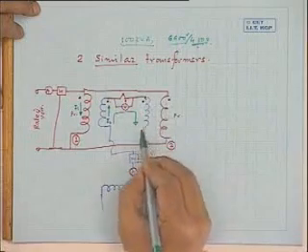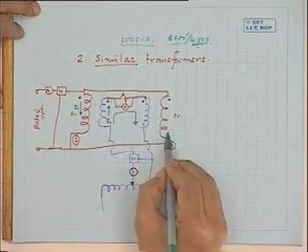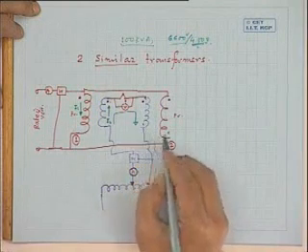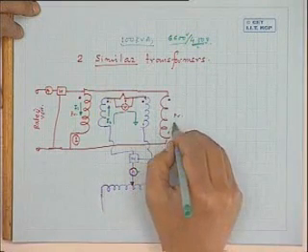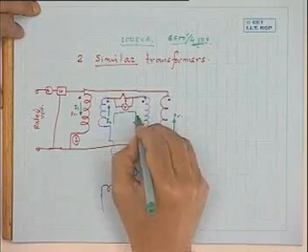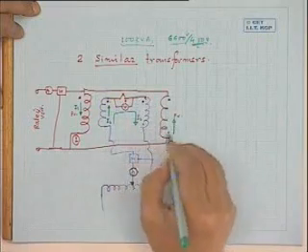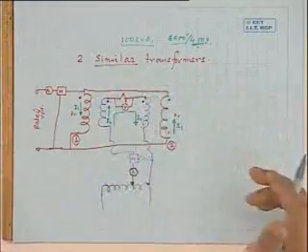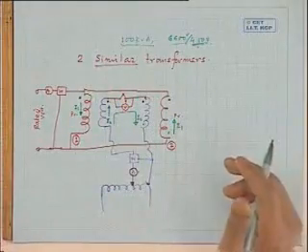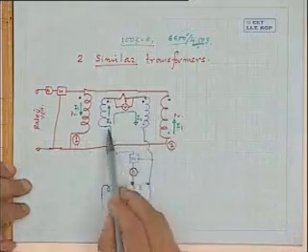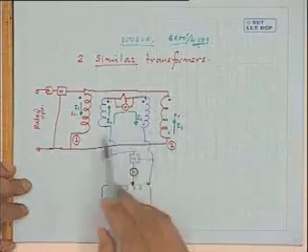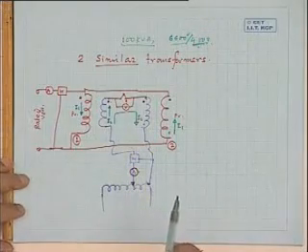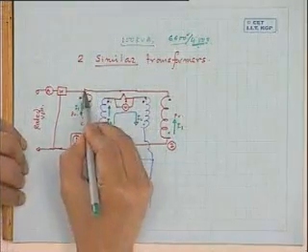Now for this terminal here, for the second transformer, secondary current, see these 2 are dot, means the other 2 are also dots. That way if you think, through this current is coming out. Therefore this one is I2 because they are series connected, and this one will be I1 because the transformers are similar, turns ratios are similar. So the current distribution in the secondaries and the primary windings will be in this fashion, like this.